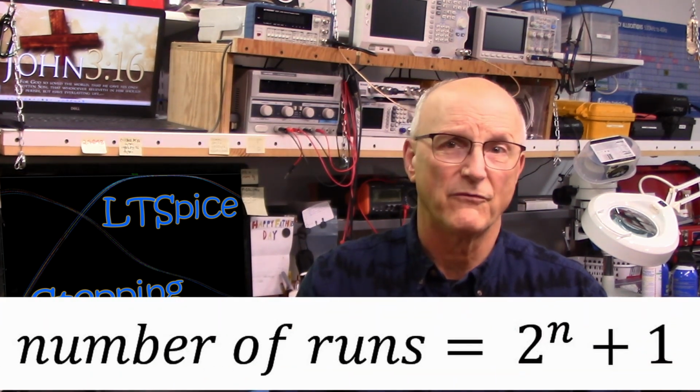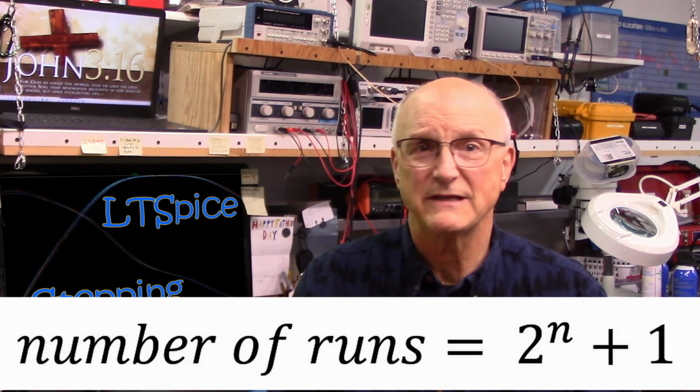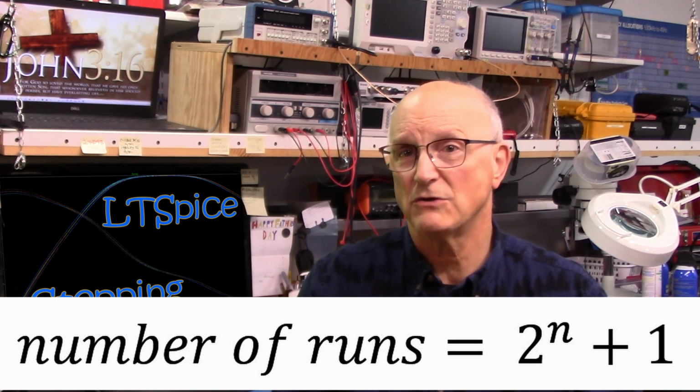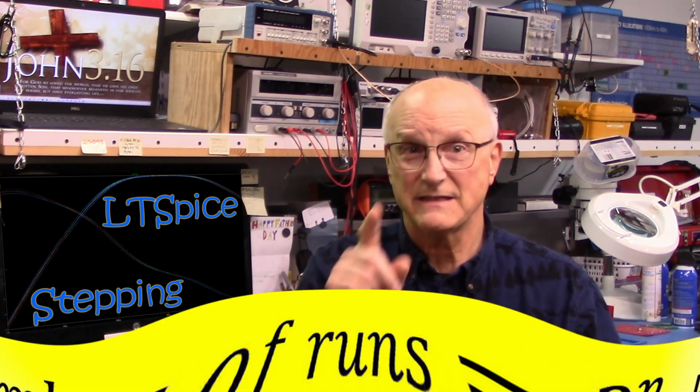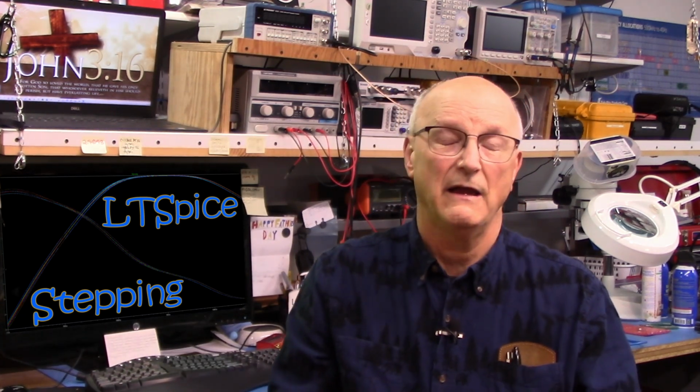The total number of runs can be calculated using this following formula. The number of runs is equal to 2 brought to the nth power plus 1, where n is the number of components that you've chosen to step. Now, this is important to remember. You're going to need it later. This will require us to define some pretty special PSpice functions and assign some pretty funky looking values to our components. So hang on, here we go.